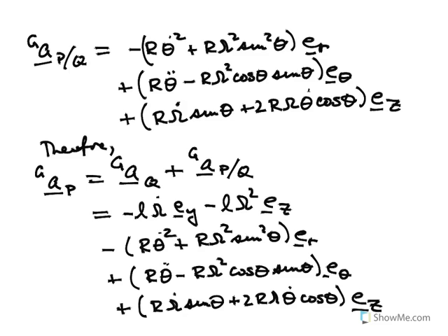So you'll actually see here that again, we've got two parts to the vector. One part gives us the acceleration of Q, and the other part gives us the acceleration of P relative to Q. And the manner in which we decompose things is we take the derivatives separately for each part of the vector, and then we combine them when we're all done.